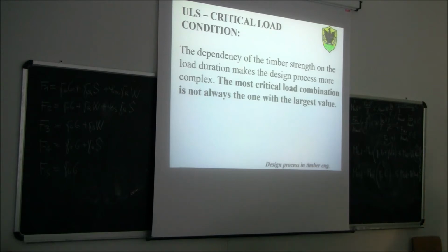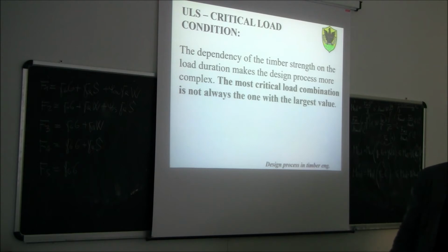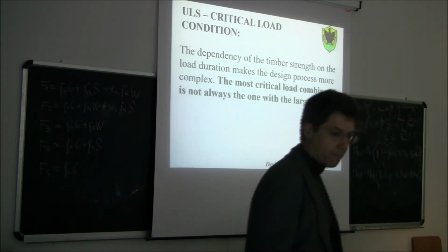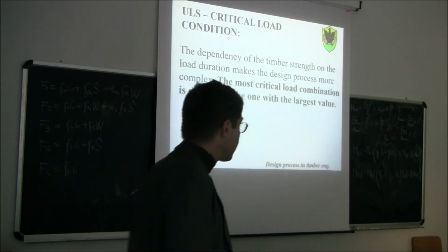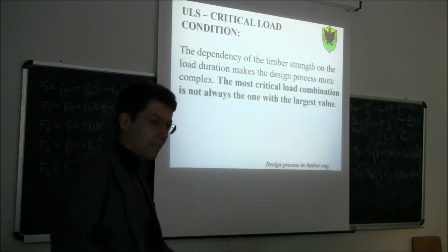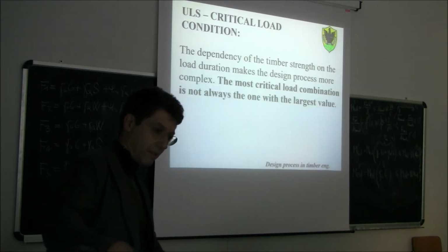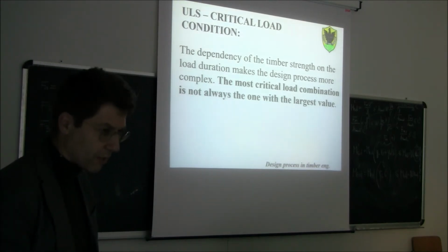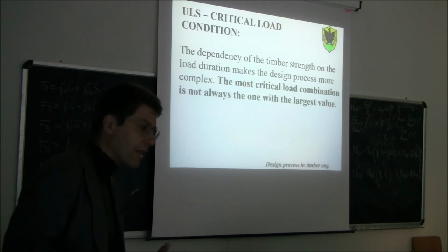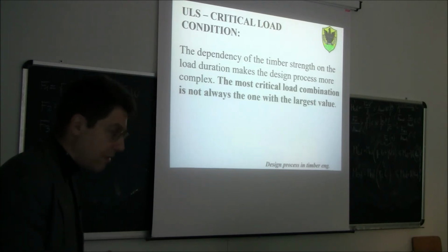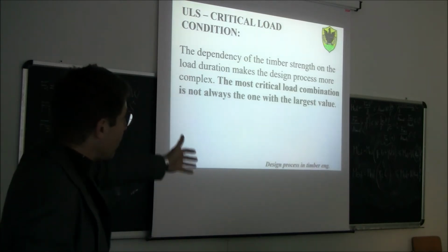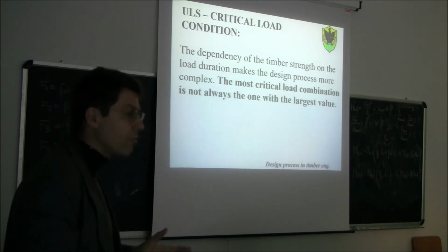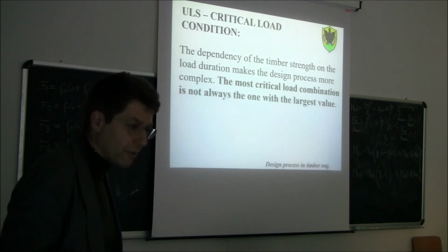How can I recognize out of 20 load combinations the most critical one? The C is the capacity, somewhere related to this capacity. Since all 20 load combinations shall be less than a constant value, which one should I take?